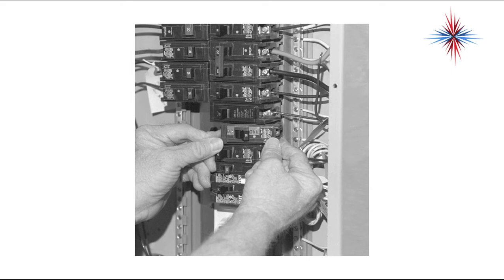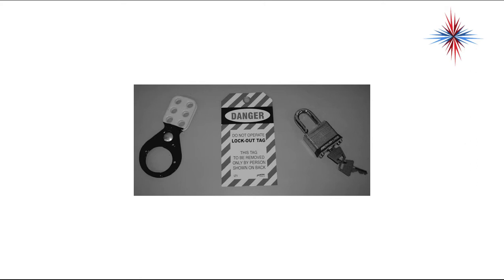Okay, so again, we have our breaker panel. The breakers snap in. You see that that's what this gentleman is doing, snapping a breaker into a panel. Again, there's no power on this panel, or this gentleman would not have his hands in here like this. It's an extreme shock hazard. Have to be able to disconnect and lock out. Do not forget, lock out, tag out. If you cannot see that panel, if you're working on equipment, or if you have any doubt whatsoever, the rule is you have to lock it out.